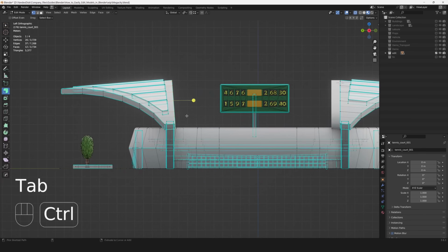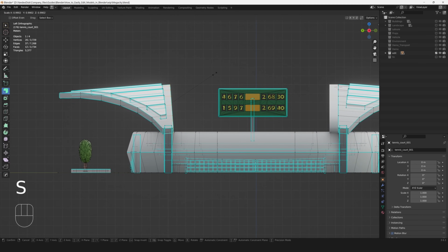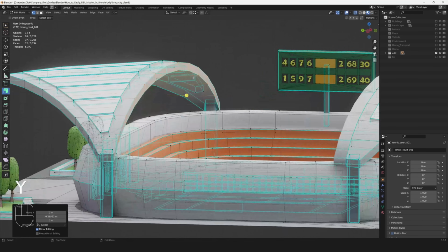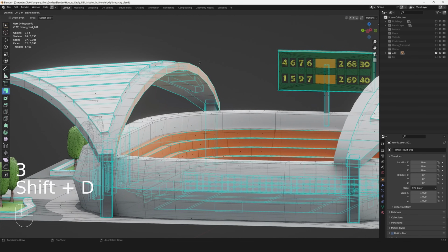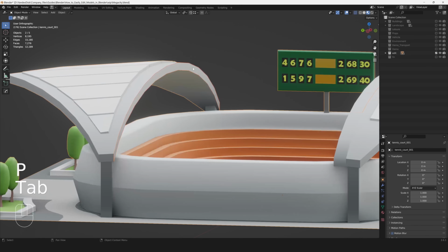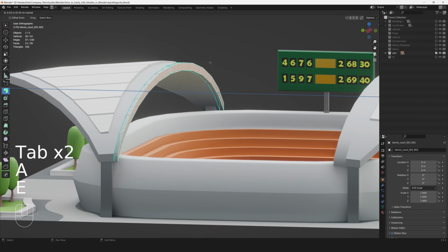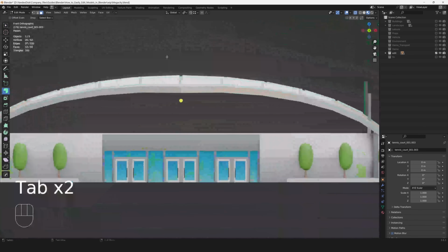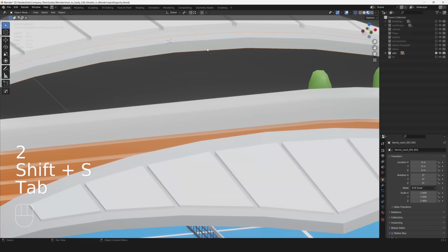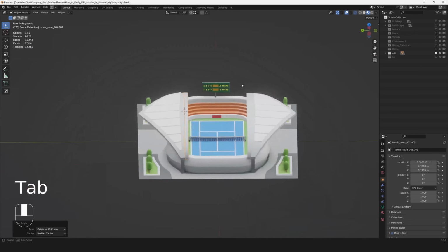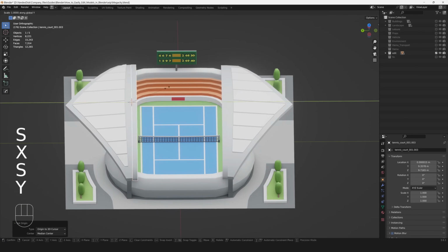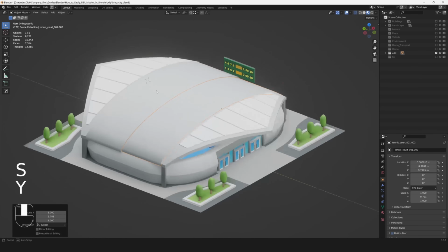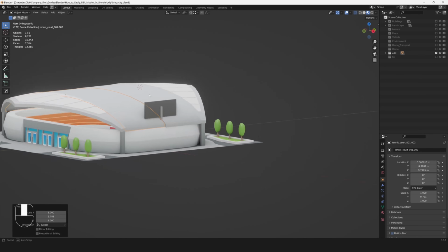Now we should do the same for the second part of the object. By the way, with Ctrl you can deselect vertices, so I will deselect all of the other vertices in the roof. Now I will copy them and separate them. And the next step is again extruding. If you cannot extrude it to one unit, that means you should extrude it on -1 unit, because it's on the different side. Or you can simply drag it with your arrows. The rest of the operations will be pretty much the same. Now it's ready for animation.